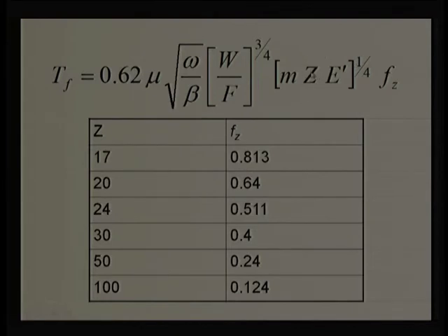Increasing the number of teeth is going to increase the TF value, but increasing Z is going to decrease Fz. So, this is more beneficial compared to this. It is only having power 1 to 4 or 0.25, while in this case the power is 1. So, we need to compare it, and wherever the benefit comes, we need to take a decision based on that.